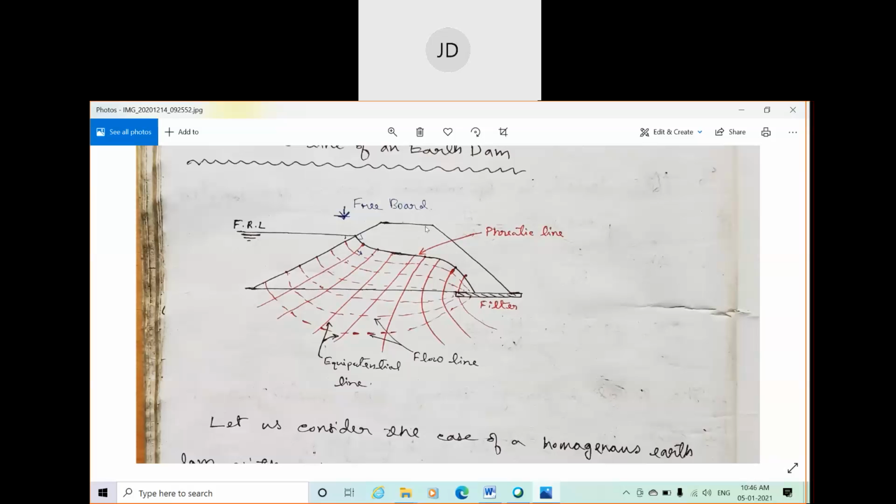So to divert the seepage away from the downstream face, one special structure is constructed at the bottom of the dam. It is made up of coarse aggregate and similar material having larger voids, and it attracts the seepage. You can see all the water goes through this filter portion only, and by providing the filter here, we can safeguard the downstream face of the dam. This is a very basic definition that I have given. This is the basic component of a dam. So let's go again to the problem.